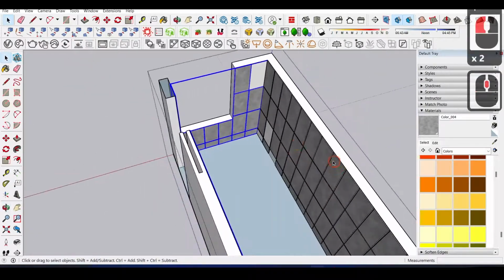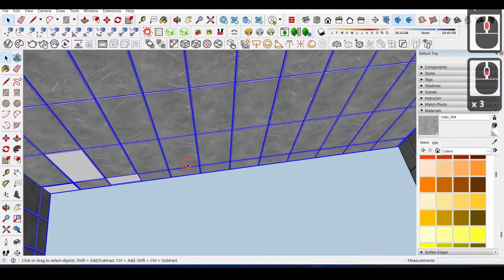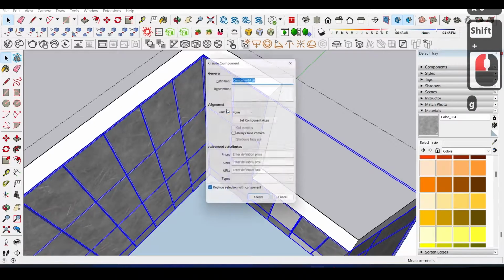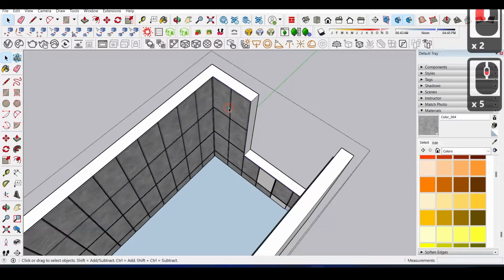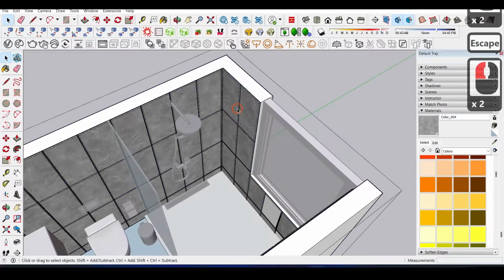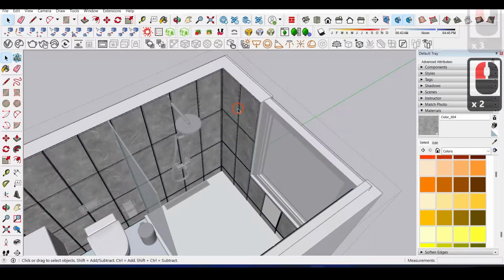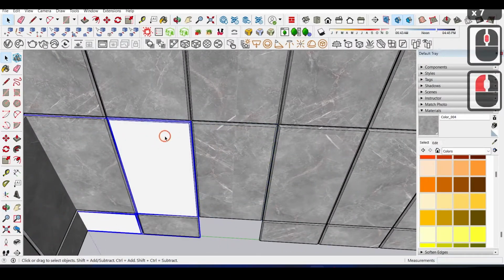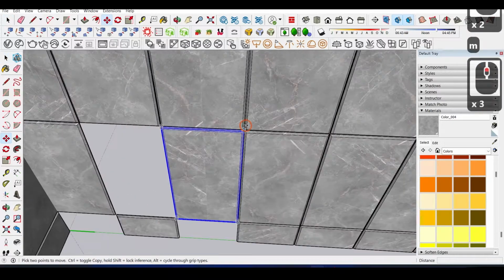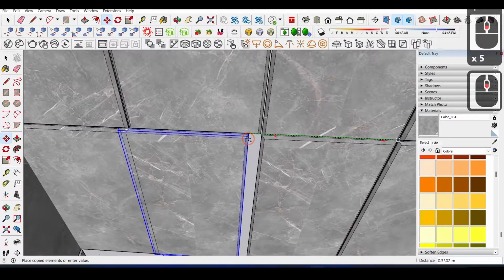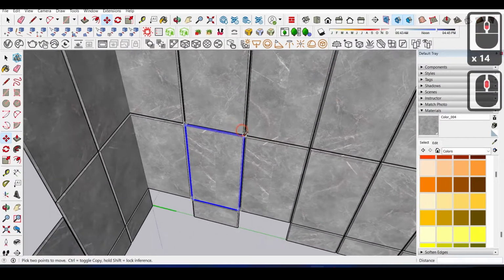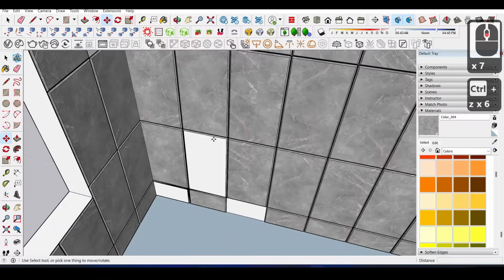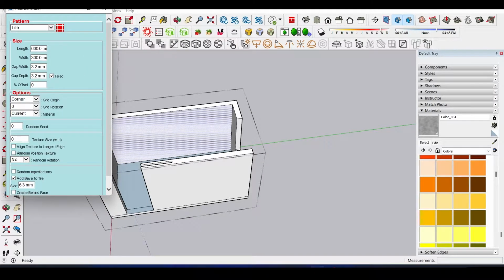Now what I need to do is I need to fill out these spaces. Creates some errors, which I don't need, so I'll just try to make them correct. Copy it from here. Maybe the bevel is too much, so let's go back to floor generator. Bevel we can do, I think 1 mm is fine.